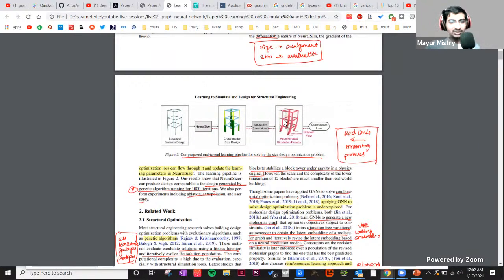There's a code provision that for a structure the drift limit is this value. So it will check whether the current drift is higher or lower than the drift limit. If it's higher, it will penalize the network and do the training so that the next time it's sizing, if it's failing, it will size a bit heavier section so the drift is within control. So this is a very high-level overview of how these two networks are trained.